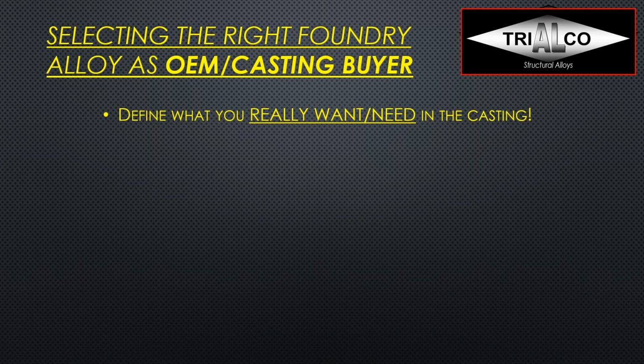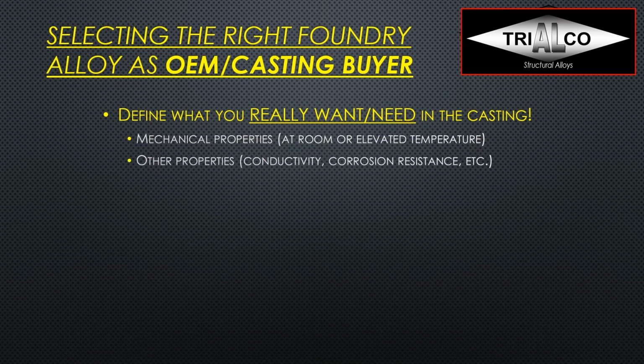Define what you really need in the casting. Usually, this is mechanical properties, and you want to define them where you need them, for example, at room temperature or at elevated temperature. Define all the things that you really need the casting to be able to perform. Any other properties like electrical or thermal conductivity, corrosion resistance, and define how you want it to be tested. Maybe even recycling content or a carbon footprint. This is something that's becoming more and more important.